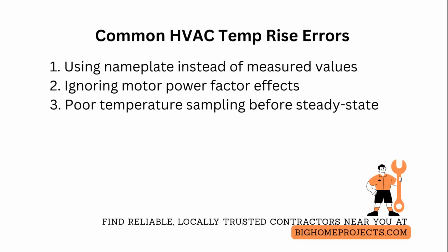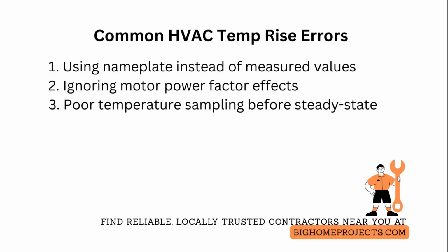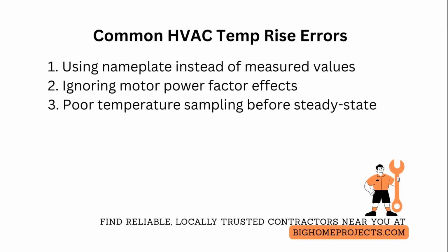One of the frequent errors is poor temperature sampling, too few points, or taking readings before steady state, causing biased temperature rise. Fix this by taking multiple evenly spaced register readings after a stable runtime and using consistent instrument placement and probe insertion depths.